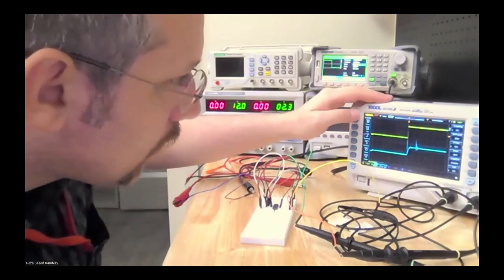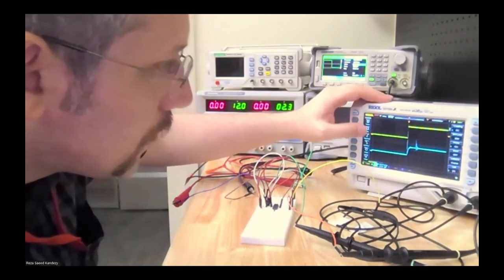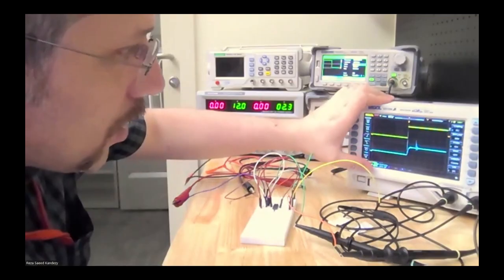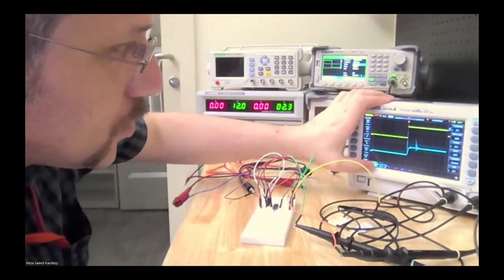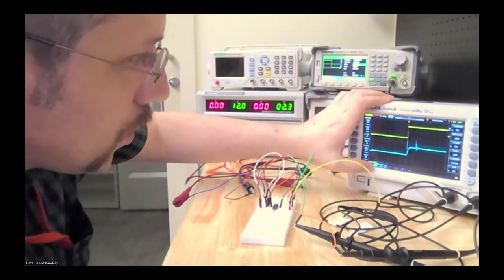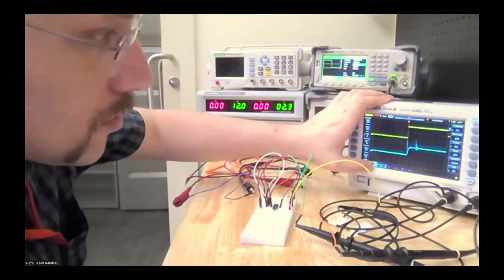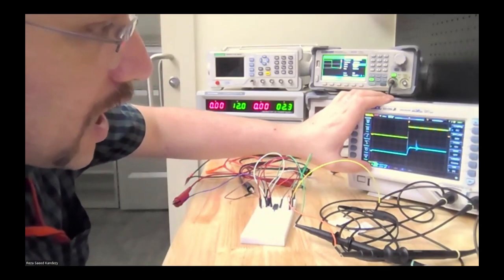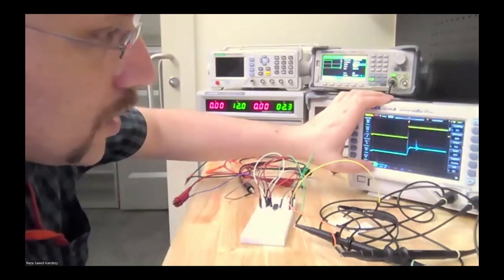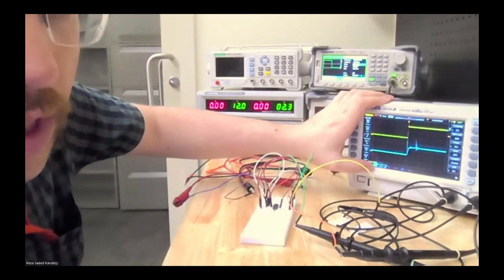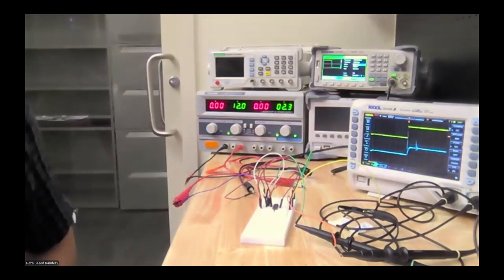And for the final value, I have 1.5 units, and my voltage division is 200 millivolts. So what I'm getting at the output is 300 millivolts. So let's calculate the slew rate.